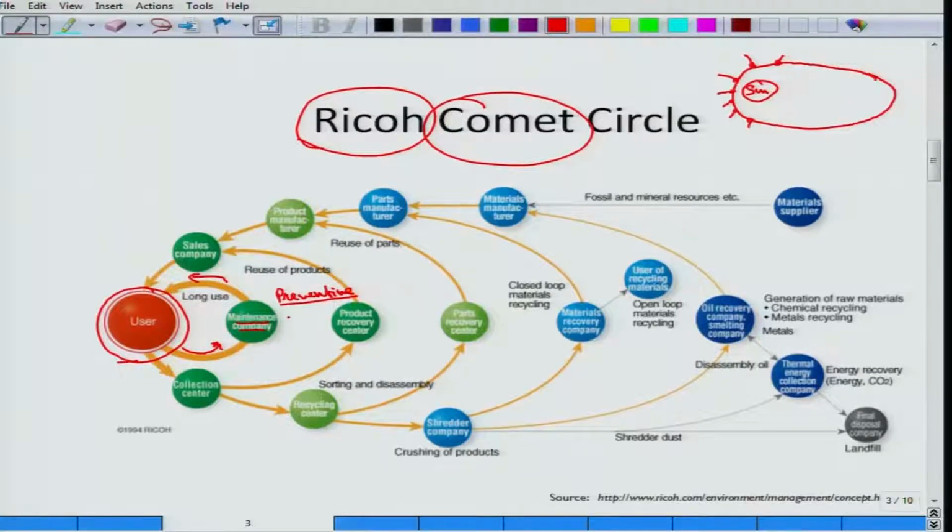So, this is preventive maintenance, you keep on getting it through the company. Then next, even corrective maintenance is there. Corrective maintenance is when some small issue comes up in the bike. For example, your bike brakes are not working well, or your clutch plates have deteriorated, your kick is slipping.